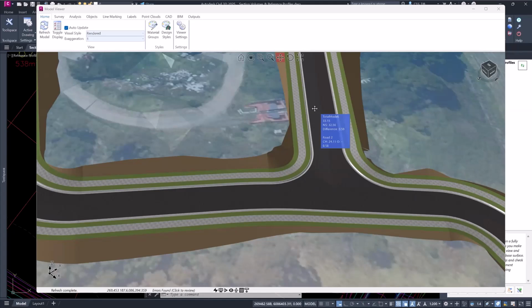So you're actually going to see the center line information used to generate the profiles for the left and the right, depending on which ones you set up. So the center line's the parent, and then you set up a relationship between that and the code you nominate, whether that comes from your template or whether you specify some sort of height and elevation change, slope or elevation change. And you can also lock regions.